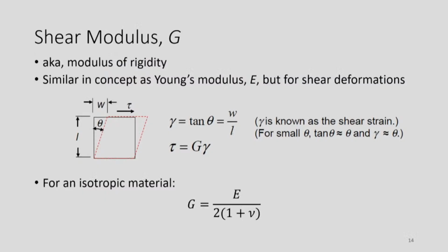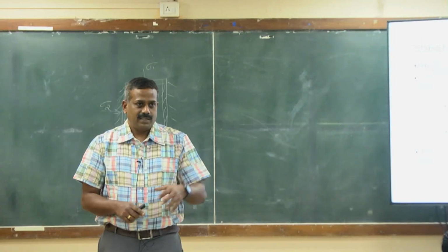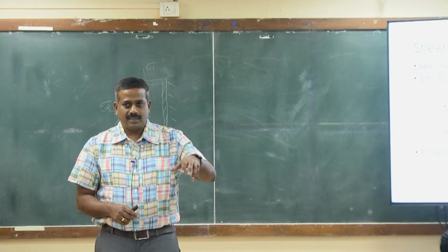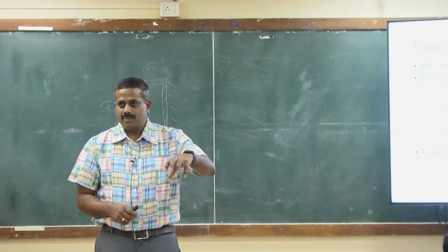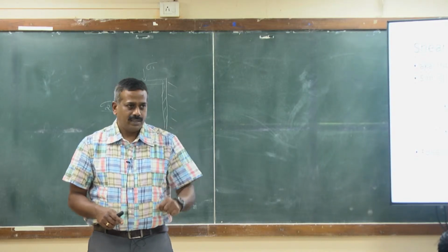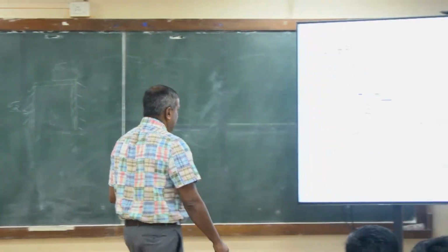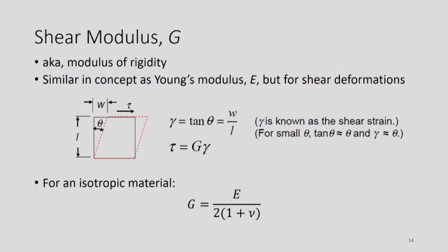Shear modulus, again, is the ratio between the shear stress and the shear strain. It comes into play with the flow of powders. You calculate the shear stress, and in the same way you can calculate the shear strain, the strain needed to make the powder move or flow. You get those two properties and then get the shear modulus.